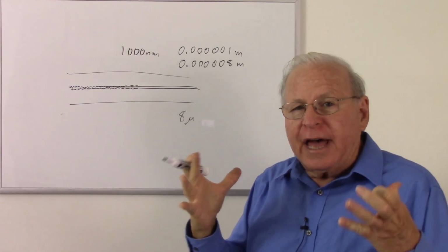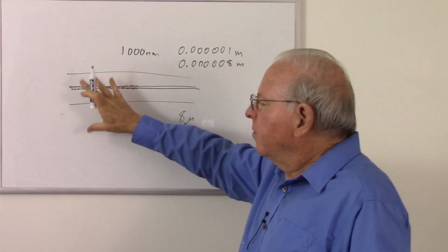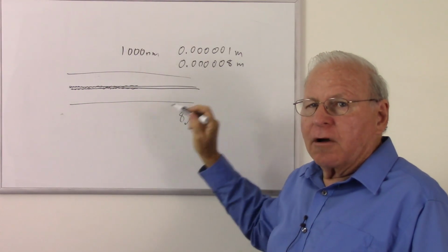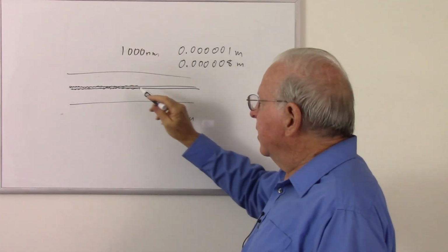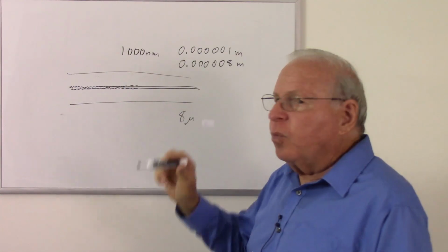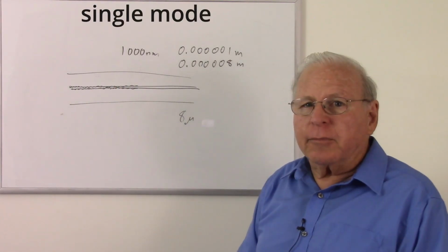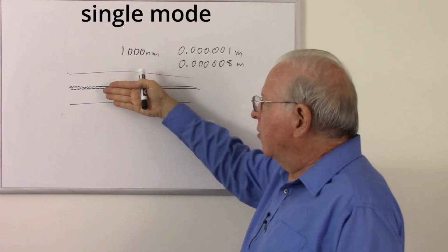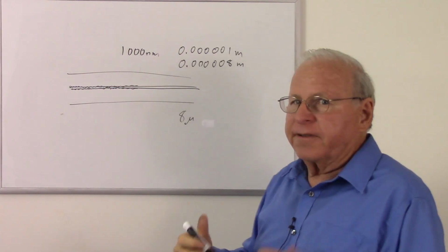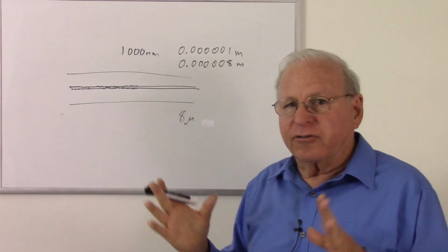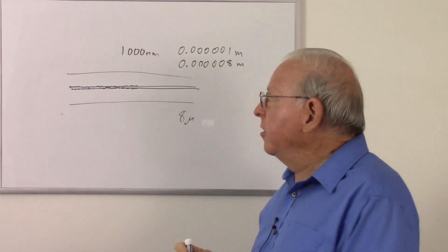So we no longer have the problem that we had with multi-mode fiber, where we have some light taking a long path, some light taking a shorter path, and we get modal dispersion, as it's called, because of the multimode fiber. So that's one way to mitigate the modal dispersion, is to use what's called single mode fiber, which once again we have a very tiny core, so that the light energy follows along the core cladding interface, and that's why we call it a waveguide. It works just like a radio waveguide, which we'll talk about down the road in communications.